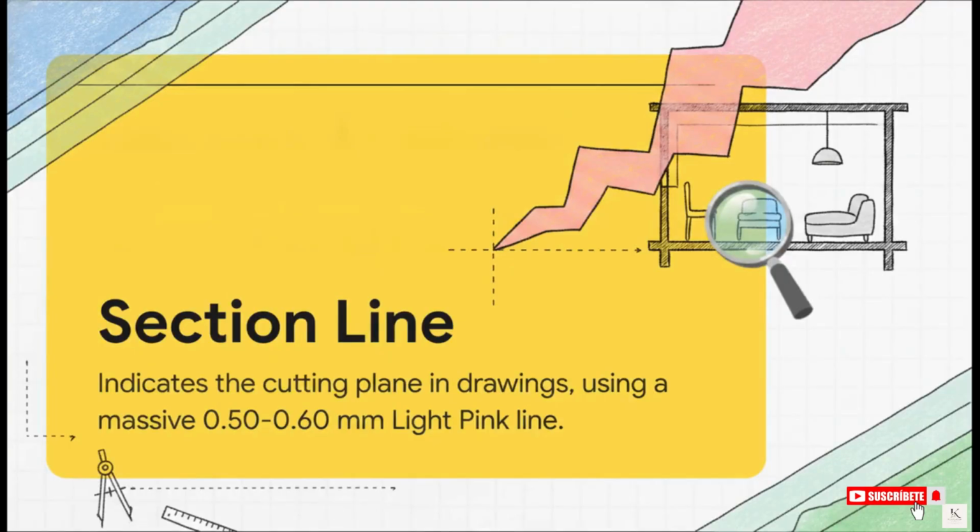But wait, there is actually one line that is even thicker, the section line. This indicates the cutting plane in section drawings, and it's highlighted in light pink at a staggering 0.50 to 0.60 millimeters. So the absolute thickest line in our entire hierarchy is the section line. Why? Well, because it doesn't just represent an object, it dictates the primary cut and perspective of the entire drawing. It screams out to the viewer exactly where we slice that space in half.